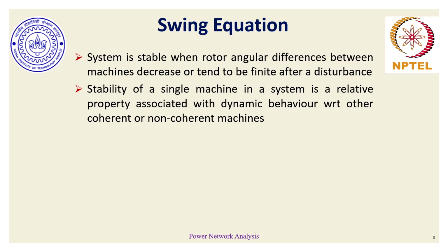So essentially, the swing equation, what we have discussed: in order to understand transient rotor angle stability analysis, we have to first of all solve these swing equations, and the more swing equations there are, the more time is involved. So there have to be ways of figuring out how the number of swing equations can be reduced, because these are differential equations.